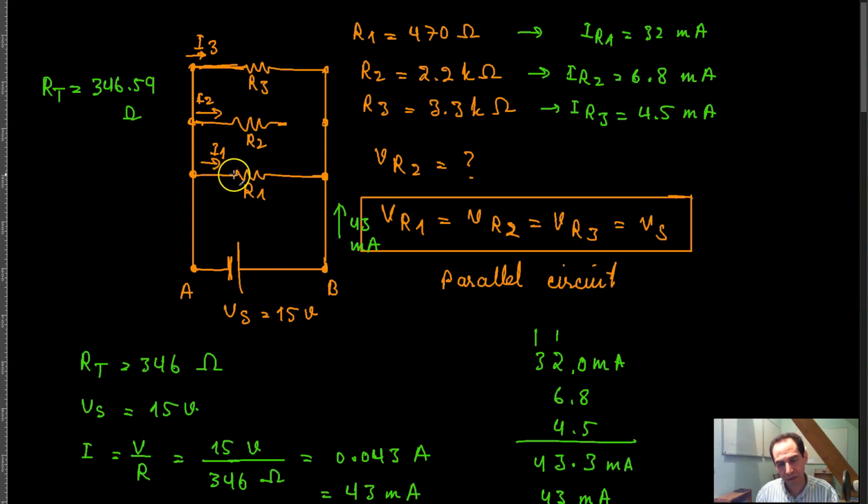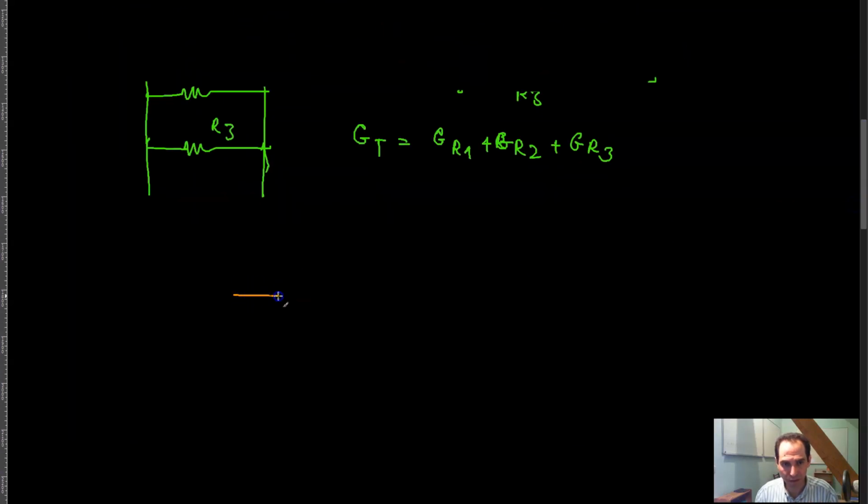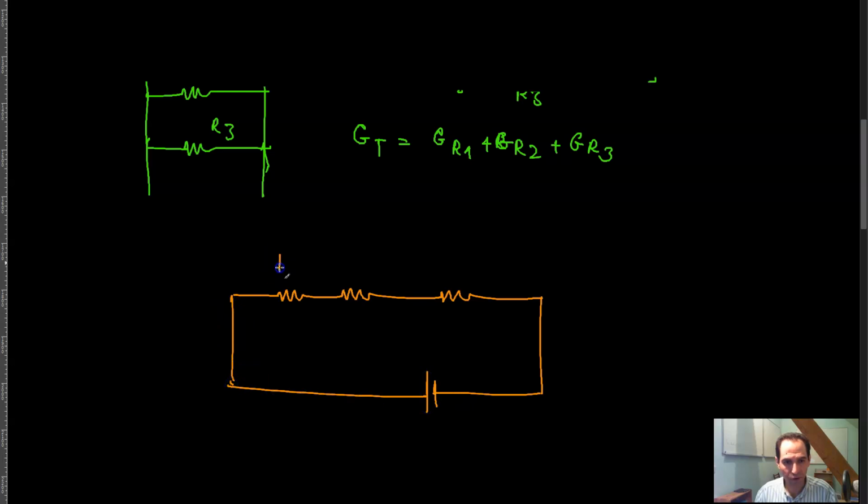Now if it was a series circuit, suppose you have a series circuit like this with R1, R2 and R3. If I cut this resistor R1 from here, the current through the whole circuit drops to 0 because the circuit is now open. Or suppose that I shorted this resistor R1 like this. Since the resistance in the circuit now drops, you have less resistance, so the current going through the circuit would increase. So this is a series circuit.